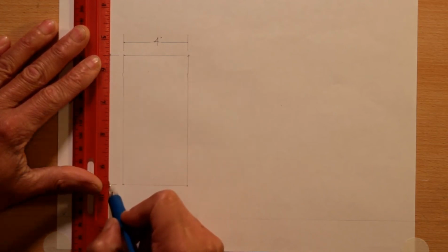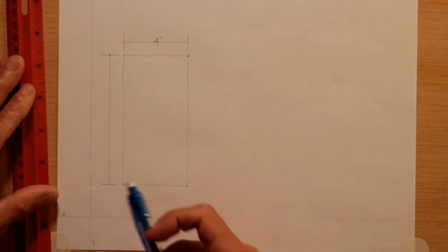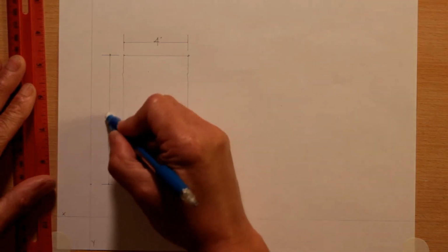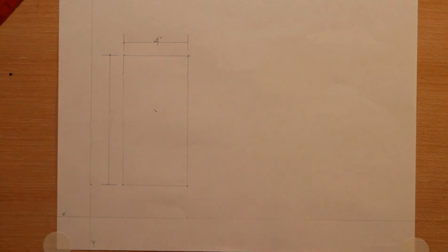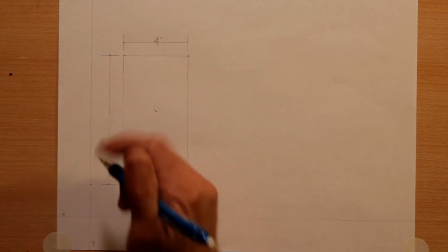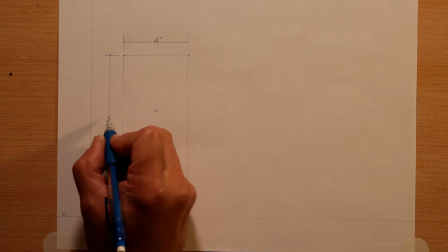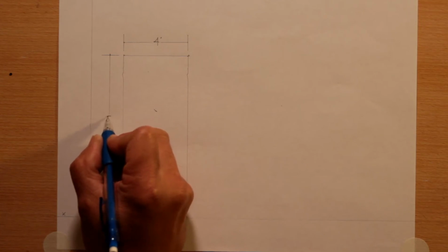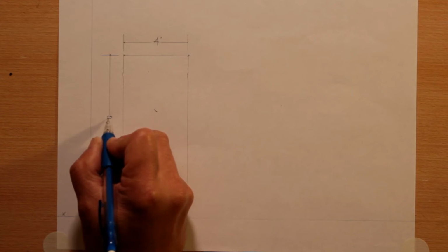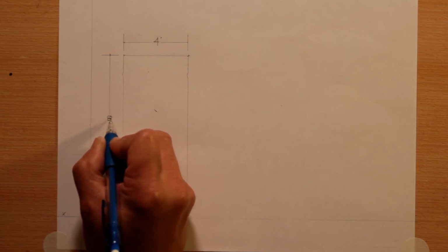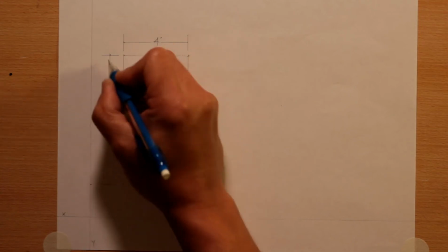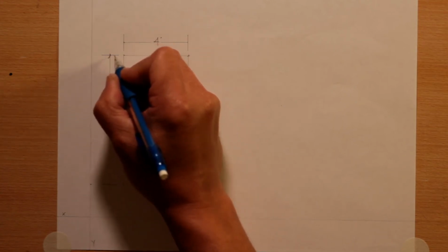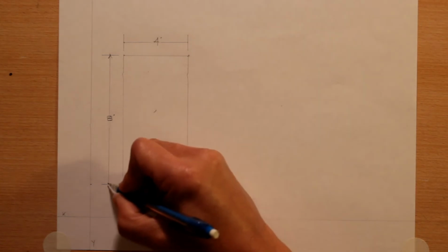On your drawings in the future, your number 8 would be drawn horizontally. But for this exercise, we're going to keep it vertical just to keep it simple. To finish off your dimension lines, we are going to put in a few quick tick marks to create arrowheads. The points should touch the extension lines.